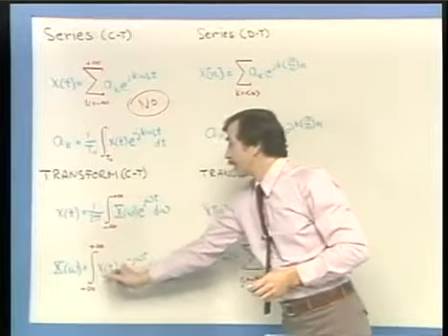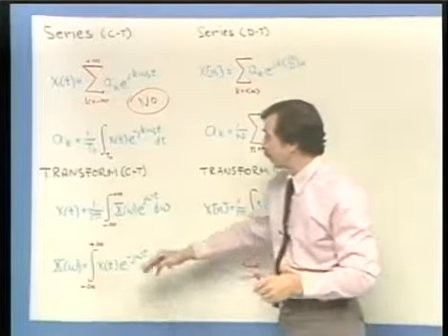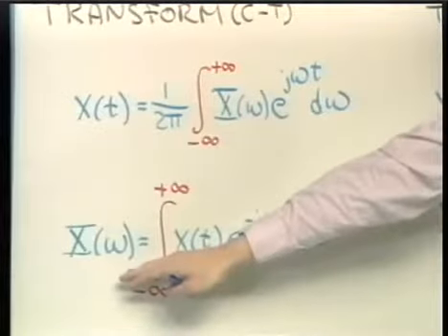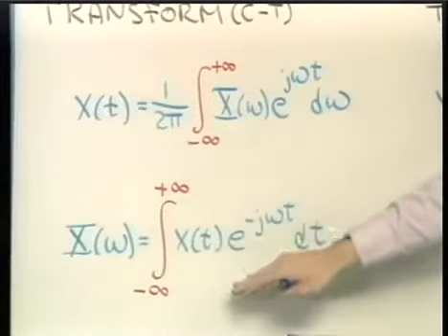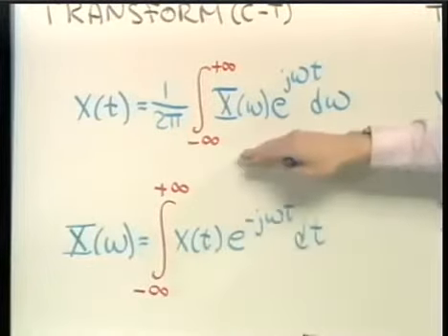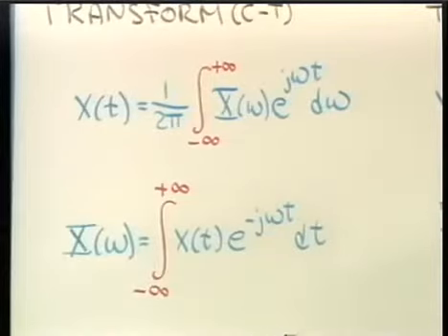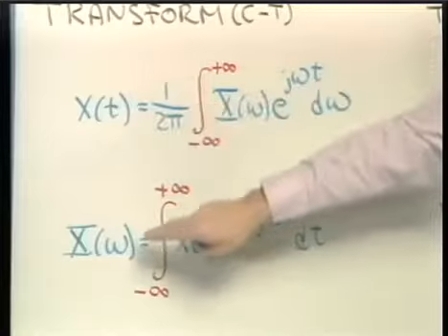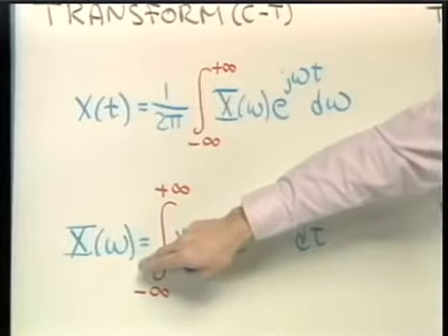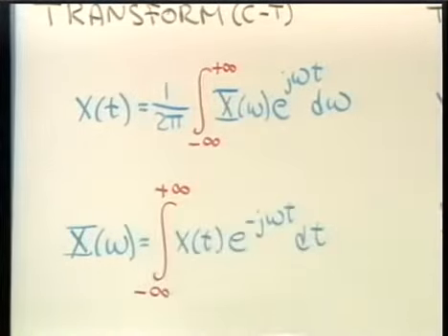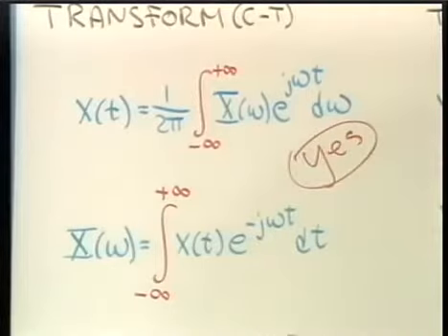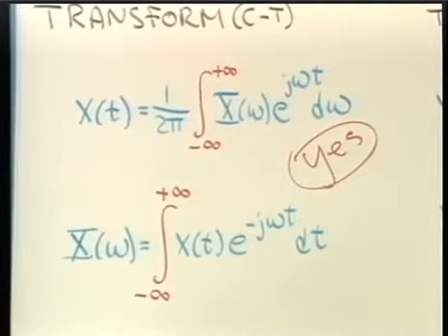However, for the continuous time Fourier transform, we're talking about aperiodic time functions and aperiodic frequency functions. And when we look at these two equations, we see very definitely a duality. In other words, the time function effectively is the Fourier transform of the Fourier transform. There's a little time reversal in there, but basically that's the result. And in fact, we had exploited that duality property when we talked about the continuous time Fourier transform.